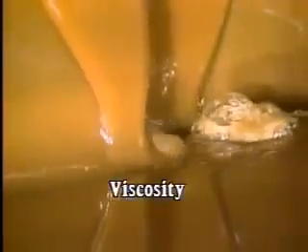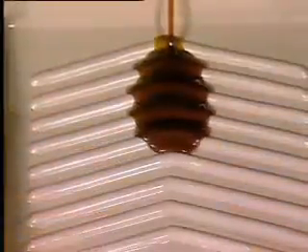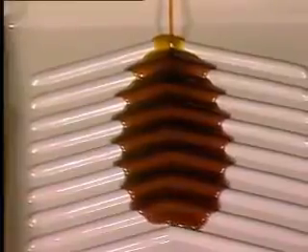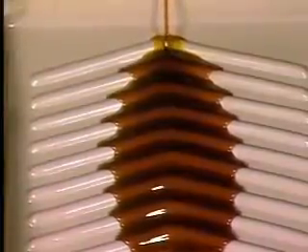Oil is a liquid lubricant made from a synthetic substance or from petroleum. Oils made from petroleum are natural lubricants. Natural lubricants are the types most widely used in industry. One characteristic of oil is its viscosity. Viscosity is a measure of a liquid's resistance to flow and is an important consideration for determining the suitability of an oil for a particular application. A thin liquid, such as penetrating oil, has very low viscosity. There's very little resistance to flow, so it flows easily. A thick liquid, such as gear oil, has a high viscosity. It has a high resistance to flow.